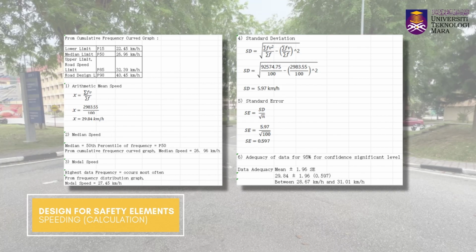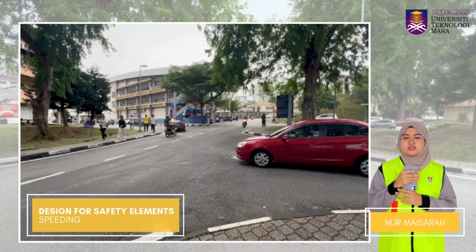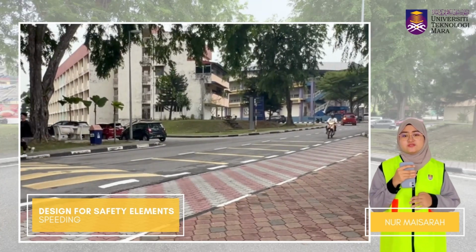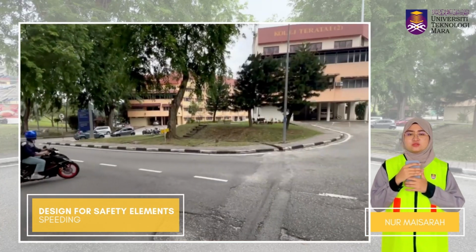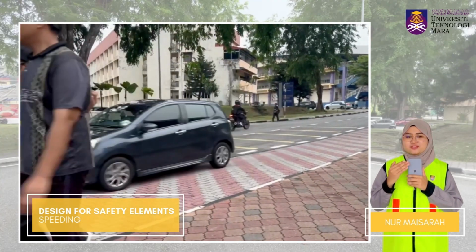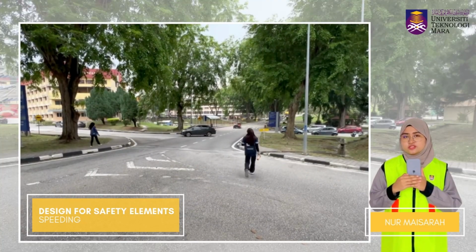The arithmetic mean speed calculated was 29.84 km per hour, and the median speed, which is the percentile of frequency at the P50, is 26.69 km per hour. The modal speed, which is the highest frequency data, is 27.45 km per hour. The standard deviation and standard error were also calculated to analyze the adequacy of the data for a 95% confidence level. Based on observation of the road intersection, we can see that there is no speed limit signage and the speed bumps on the road are not efficient. This could cause several effects, such as drivers being unaware of the appropriate speed, and it could endanger crossing pedestrians and cause conflicts between vehicles.